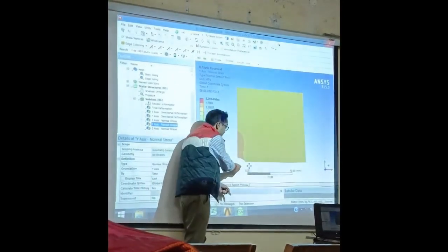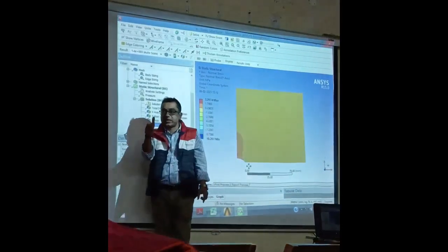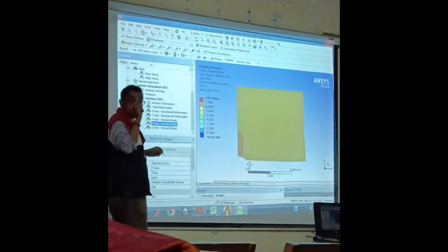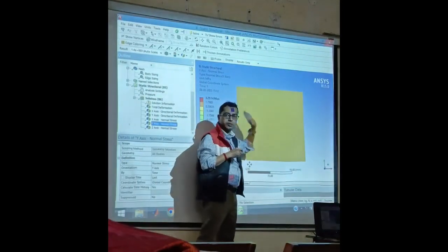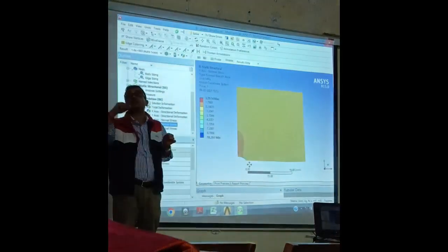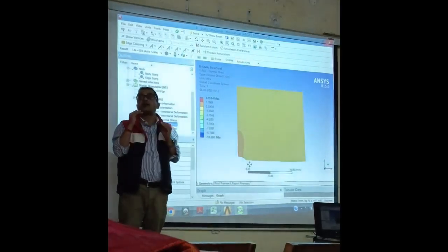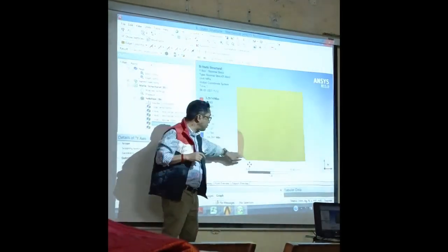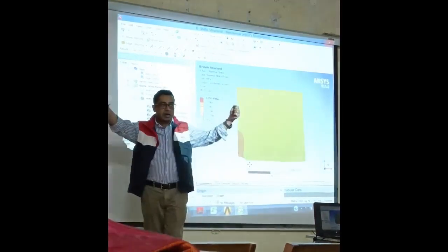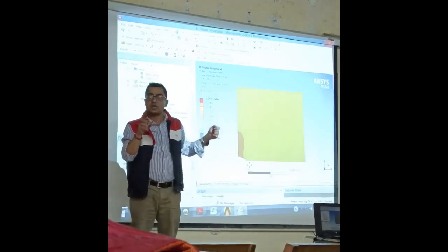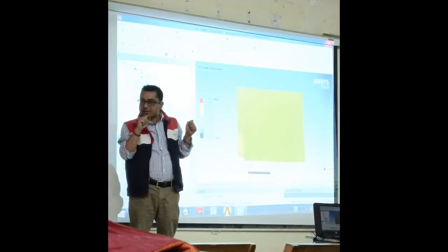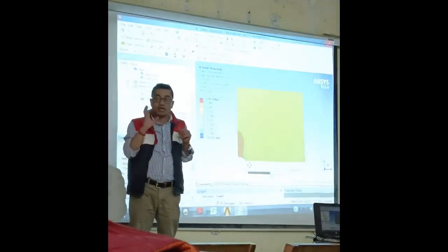Now, if the ellipse is like this, the effective area is less. So if I consider the load path, the imaginary path which is carrying the load from this side to this side, left side to right side, that load path is being disturbed. If there is no circular hole or cutout, the load path is always a parallel imaginary line. Now, once I have introduced the notch, or circular hole or elliptical hole, the load path is being disturbed near the circular or elliptical hole or cutout.